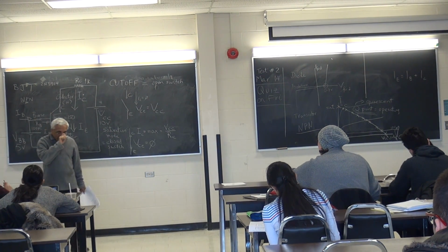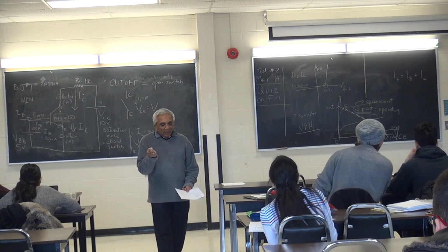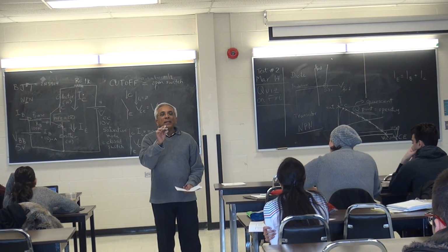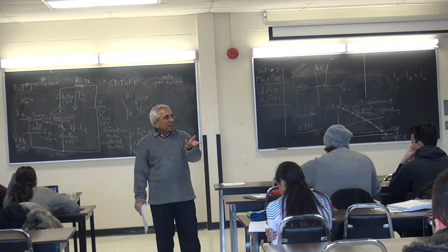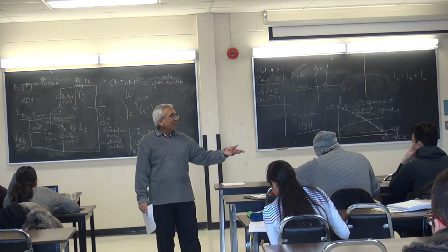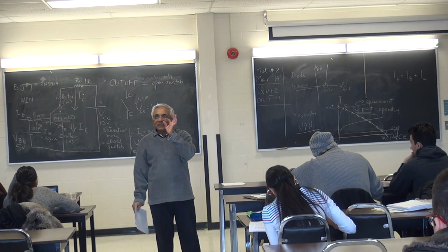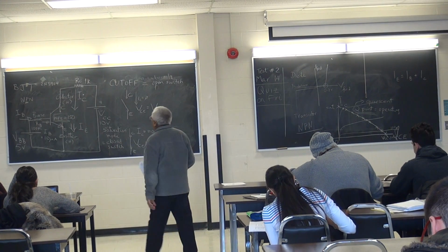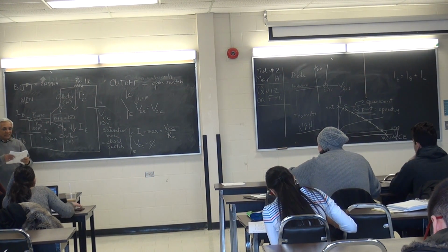Okay? That's something that you cannot determine. It is something that is inherent to the property of a transistor when it's manufactured. One day it may be 150, the next day it may be 175, another day it may be 200. That's just the way the transistors are. So in our circuit, HFE happens to be 150.